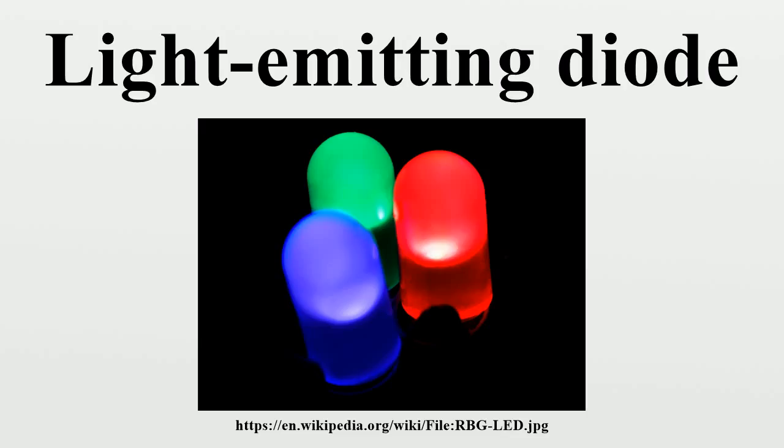The electrons dissipate energy in the form of heat for silicon and germanium diodes, but in gallium arsenide phosphide and gallium phosphide semiconductors, the electrons dissipate energy by emitting photons. If the semiconductor is translucent, the junction becomes the source of light as it is emitted, thus becoming a light-emitting diode. But where the junction is reverse biased, no light will be produced by the LED and, on the contrary, the device may also be damaged.